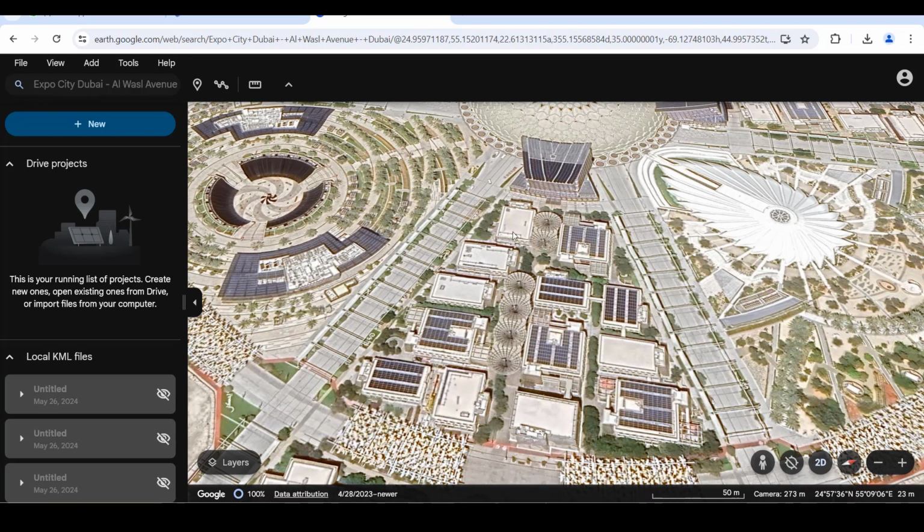If you do not follow that, in one case you will get all of these sitting correctly in your file because you did it manually. But in another context, if this building and that building try to link each other, they will not come at the correct distance, location or orientation. So that is the main reason why we use the shared coordinate system in Revit.